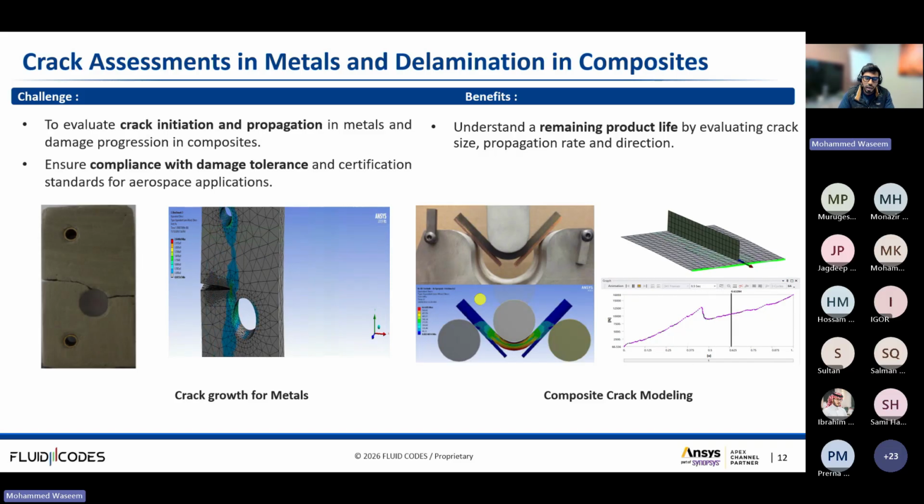So having said that, how does this help us in damage tolerant design? The outputs from ANSYS can help you set allowable damage limits. Maybe you can also define inspection intervals, like how often you need to check before it becomes critical. Further, you can also add local reinforcements or even change the layup design to reduce stresses. And by performing all these iterations, you actually prove your design meets damage tolerant expectations with evidence.